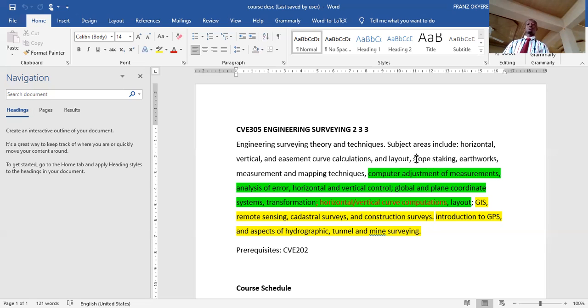I don't think it should become a big deal at all. It's like the pillars that you have on the site. The pillars have numbers associated with them. When you set your instrument on one, that is the coordinate that you are on. Then you can measure to another one, and then you can start working from that.